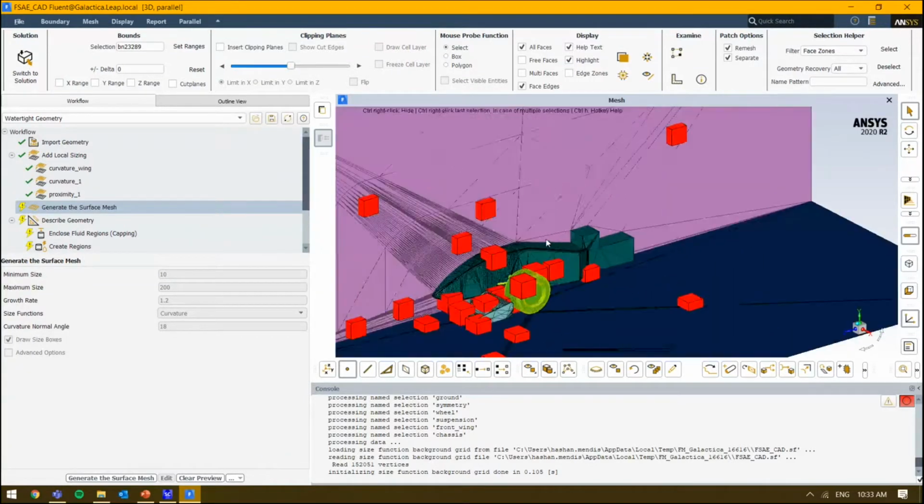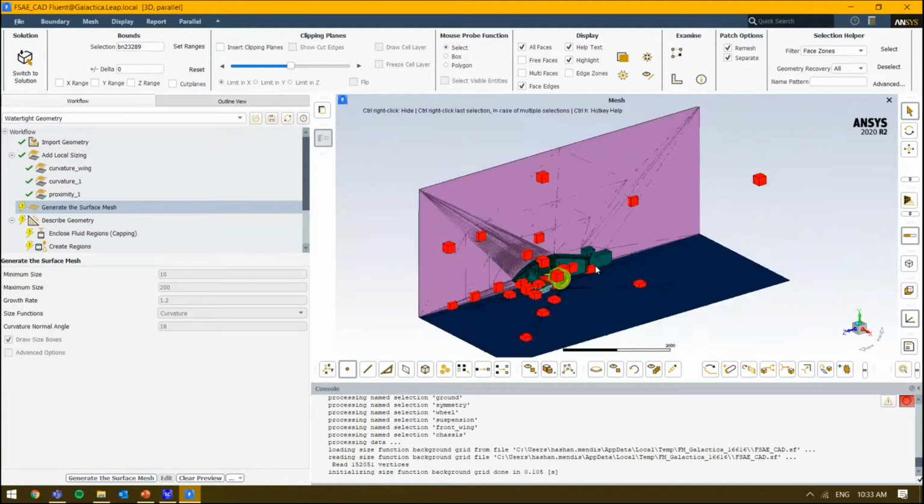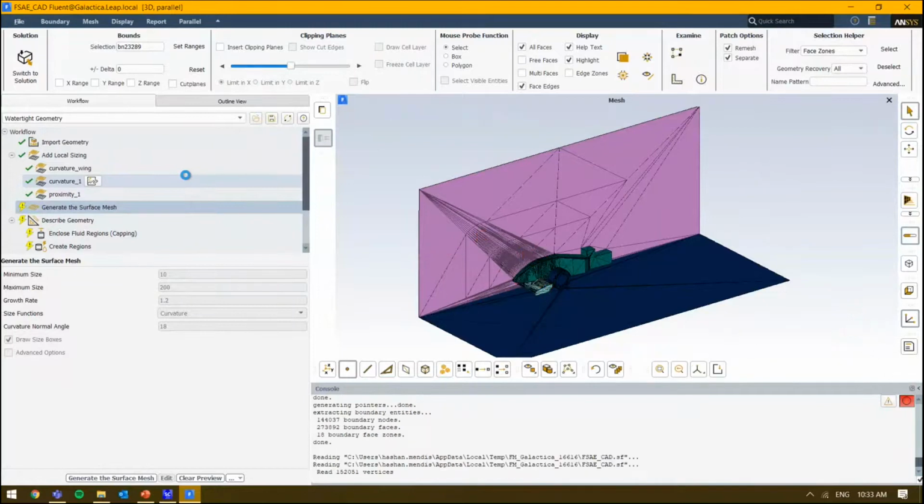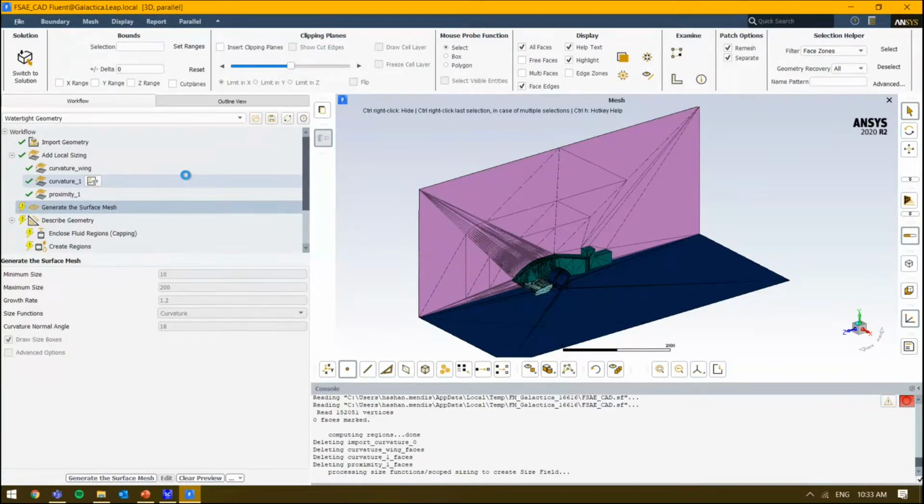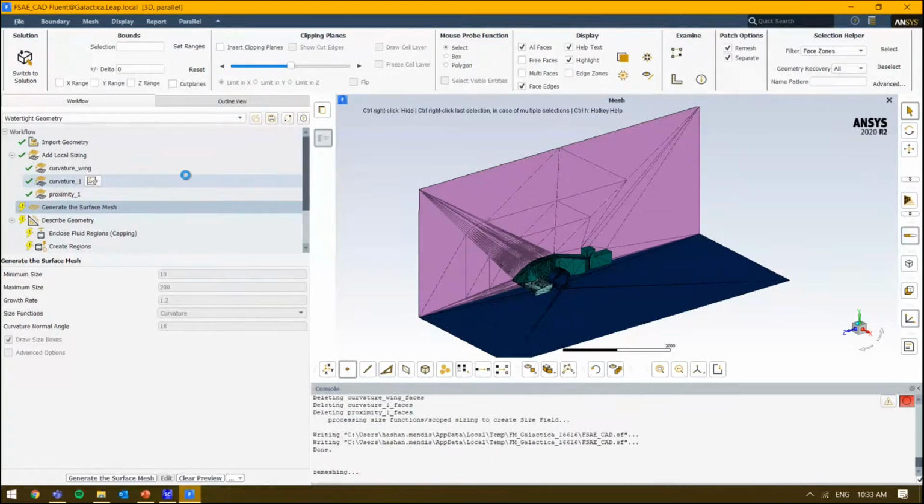Generally with this stuff, like I was saying before, I generally start with a coarse mesh with some geometry, get my boundary conditions acting as I expect, and make sure that things are going in the right direction. And then if I'm happy, I'll go back and actually start to add refinement. Everyone works a little bit differently, so I'm sure when you go about it, you'll figure your own way out.